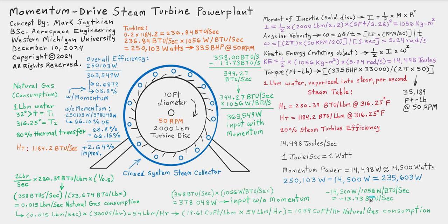So again, that does come to a 4%, see, 1 minus 0.96309, that comes to a translation of 3.96% fuel savings. So the efficiency is up by 2.64%, but the fuel consumption decreases by about 4%. So that's not a linear relationship.